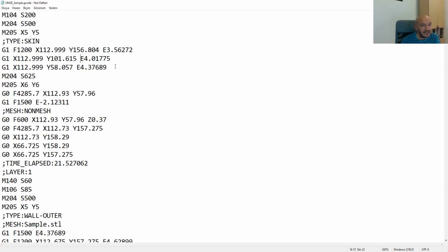And then what is done after this is printed, we do some retraction. We are retracting the material, and then we are doing a fast travel motion, and we are again depositing some more material to here. It's switching the mode of deposition, and then performs another deposition. Then next we switch the layers.